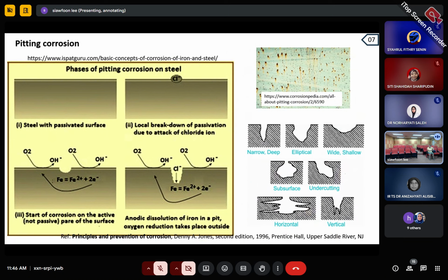Of course, some people do two studies. One is the accelerated one, and the other they actually leave there for years. For example, my boss before, who has retired already, had concrete that lived there for 20 years, as long as she was working there, to compare with the accelerated corrosion, and they can do a kind of comparative study.